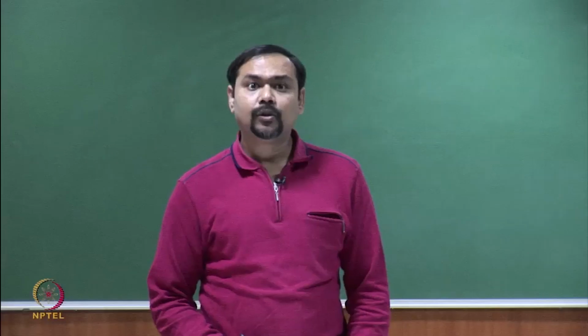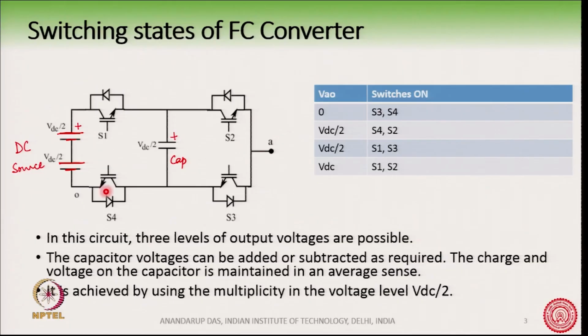You also note that these two switches must be operated in a complementary fashion, otherwise you are going to short circuit. And we also note that the voltage rating of all these switches here is equal to VDC by 2. The current rating is equal to the load current.